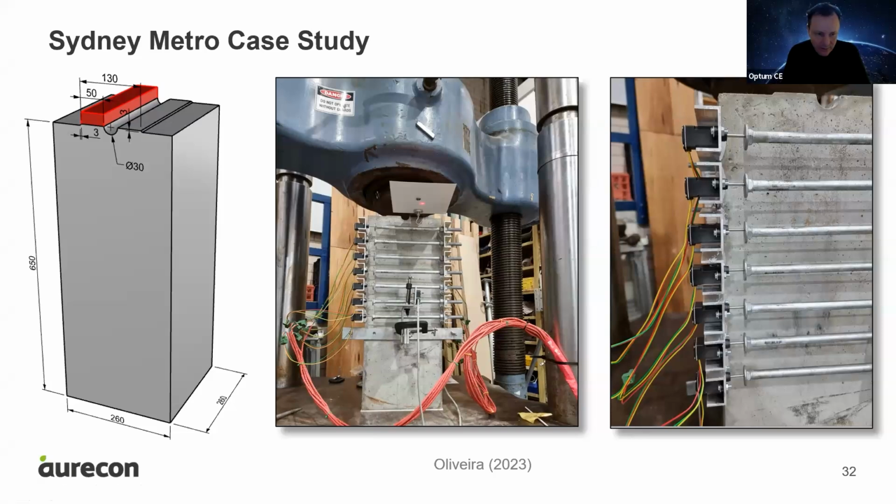Great, thanks. So I'm not sure exactly where I stopped. We went to test these joints again in the lab, and we created samples of real size, and we put a highly concentrated load. So we loaded only a 50 millimeter strip. And what you see here in these samples is that these steel bits are not confining the samples. They're just providing the base for the LVDT to be able to measure from one side to another, so I can actually monitor the expansion and the cracking of this sample. So this is not a confinement reinforcement. It's just really the LVDT. You can see here the tip of the LVDT is just contacting a little disc on the other side.